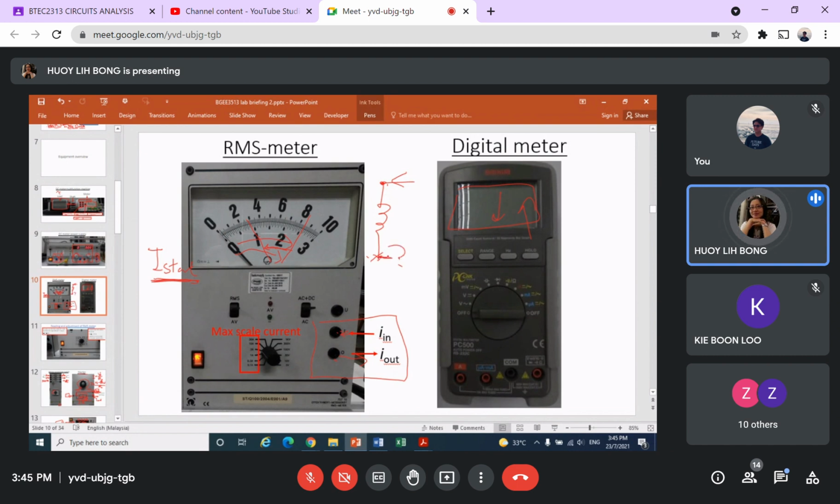If you don't connect the second leg, you have one leg, you have two legs, must have two legs. So for each measuring device, same thing. If you only connect in, you don't connect the out, it is an open circuit. Current goes in, then doesn't go out, so nothing happens. So make sure you make both connections.